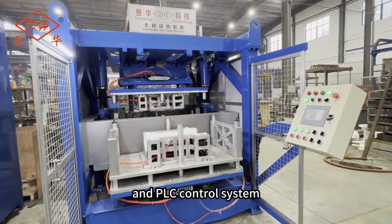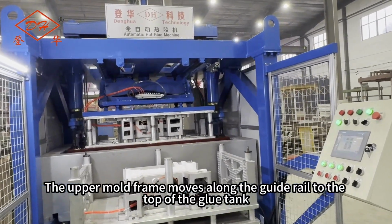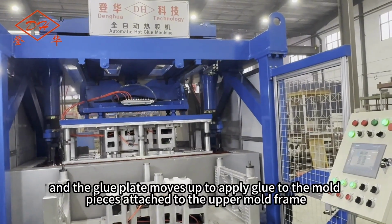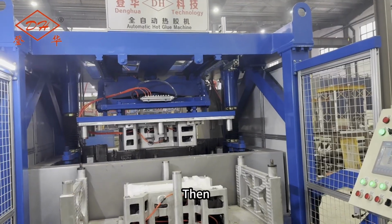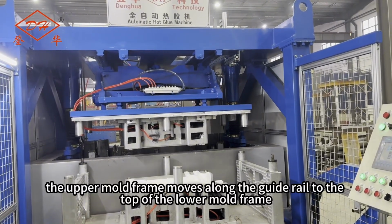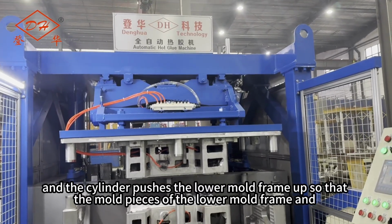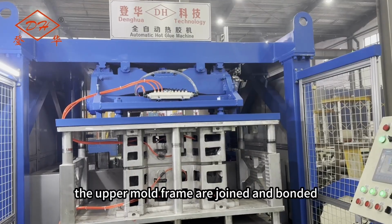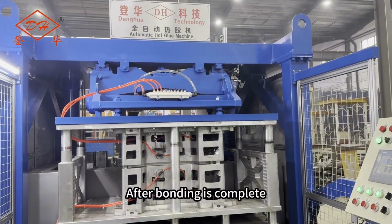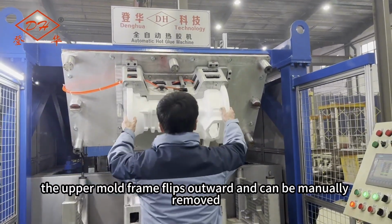and PLC control system. The upper mold frame moves along the guide rail to the top of the glue tank, and the glue plate moves up to apply glue to the mold pieces attached to the upper mold frame. Then, the upper mold frame moves along the guide rail to the top of the lower mold frame, and the cylinder pushes the lower mold frame up so that the mold pieces of the lower mold frame and the upper mold frame are joined and bonded. After bonding is complete, the upper mold frame flips outward and can be manually removed.